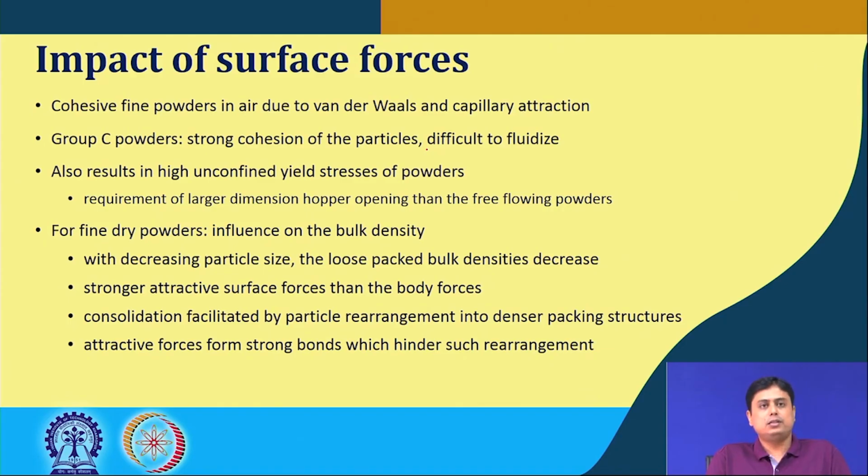Now, these surface forces also result in high unconfined yield stresses of the powders, which means it requires a larger hopper dimension for the storage and discharge of these fine particles than for free flowing powders.